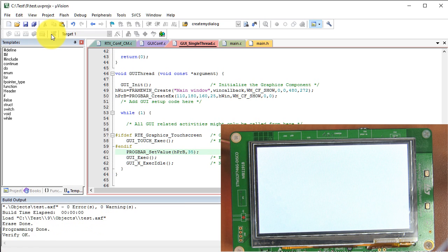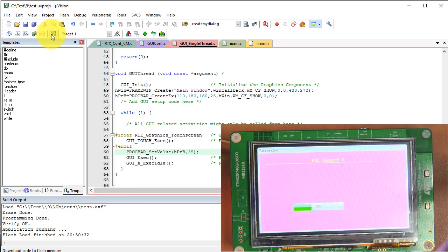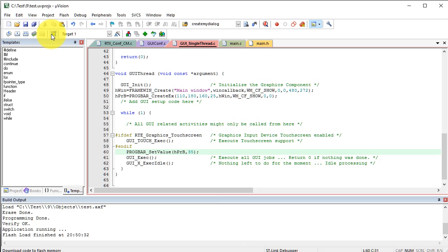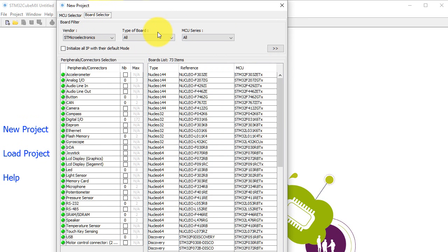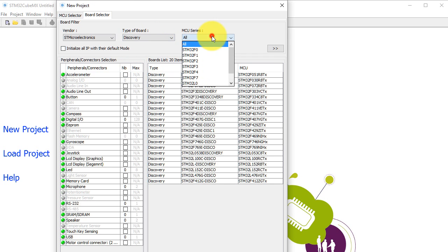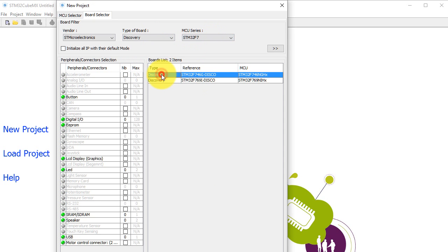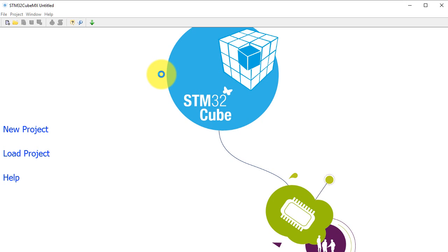In the following, we want to read a value from an analog input, let's say pin A0 from the board connector, which is the in0 input of the ADC1. In some previous videos we showed how to initialize the ADC using various methods. Here we will use the power of Cube, but it seems that its connection with Keil MDK is not yet fully functional, so we will simply copy the code from a new Cube-generated project.